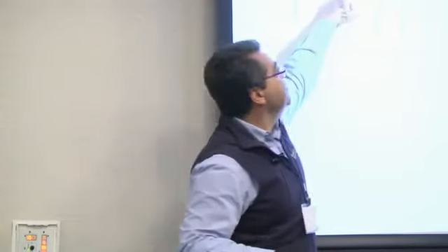And so in order to correct this situation, if you don't do anything to the system, what you do is increase the water application in order to bring this part up to match ET. And that means that the higher application rate delivers much more than needed. So you get ponding, you get fungi, you get a lot of... So system distribution uniformity is important because in some situations you might lose money. This is another system that we evaluated in another part of the farm, and it was matching pretty well.